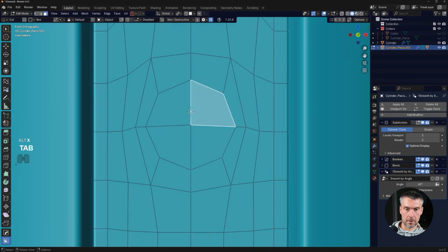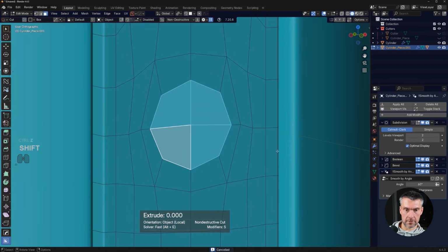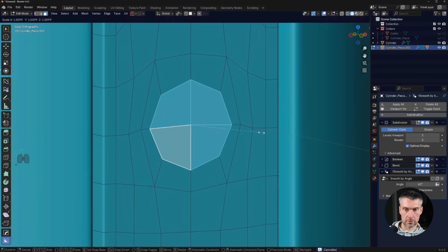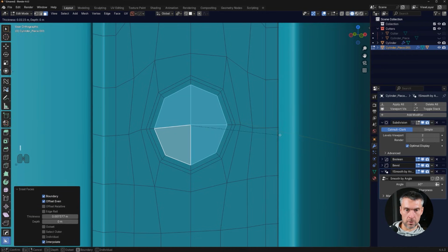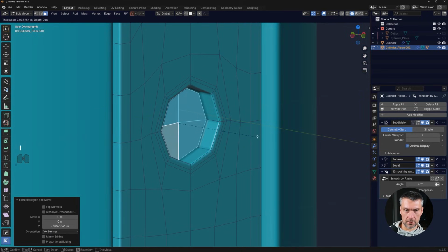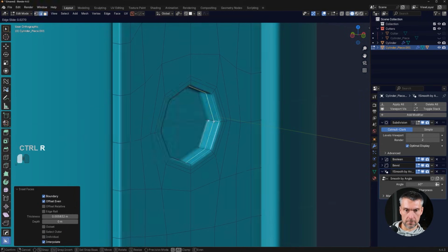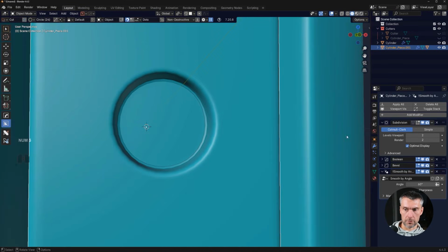And mirror. And then we're going to grab this one and scale it a bit. And then we're going to insert it once and one more time, and then extrude it, and then insert it, and then run a loop here. And then you see you're going to have a perfect circle. If you go 3 subdivisions, it's going to be smooth as hell.